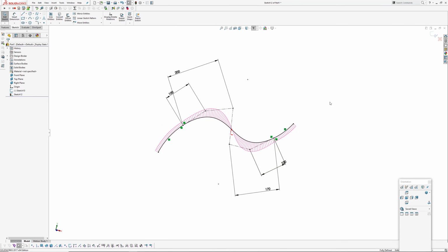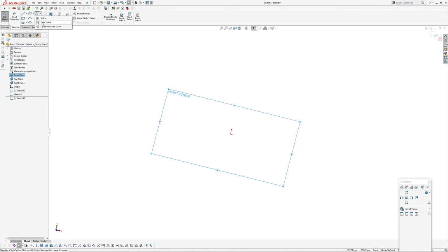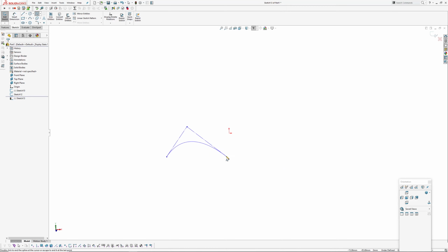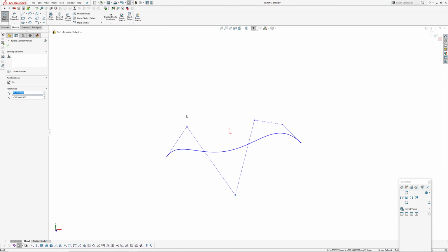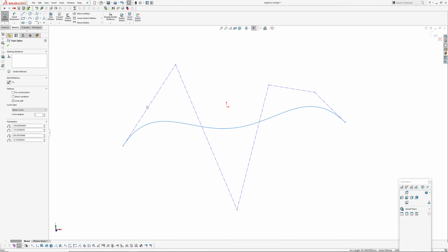Okay, I think what I'll now talk about is what the difference is between... you would have noticed in the style spline, I only talked about the Bezier curve, the spline type, which is a single span. Now I'm going to talk about the B-spline, the degree 3, 5, 7, etc. So what I'll do is I'll create a degree 5 Bezier curve, so that's got 6 points. And just drag it out a bit. Turn the curvature graph on.